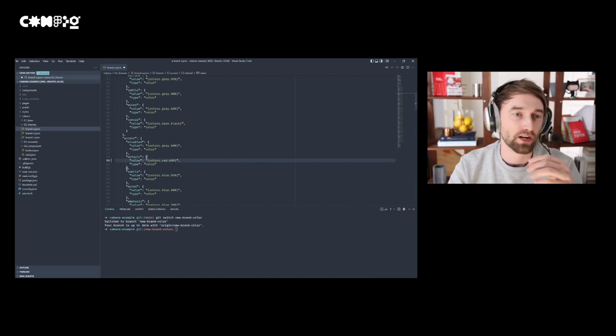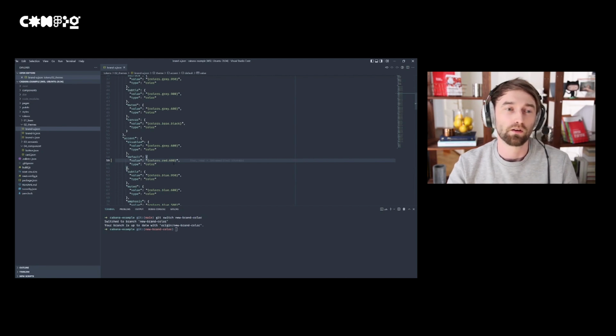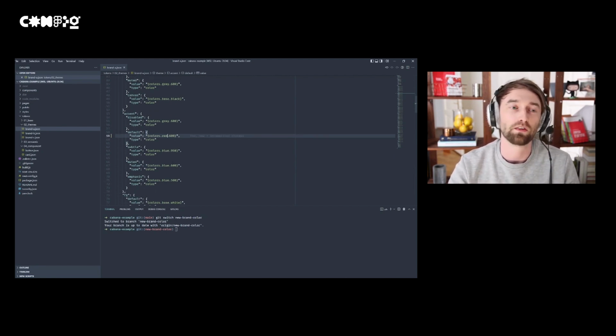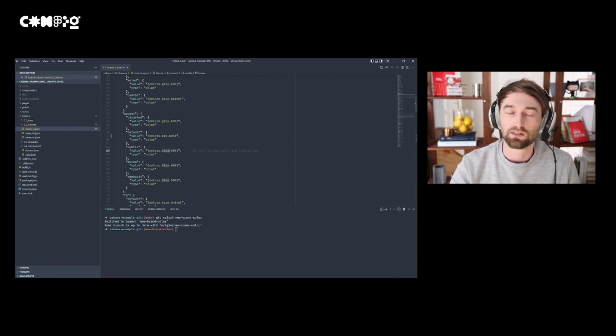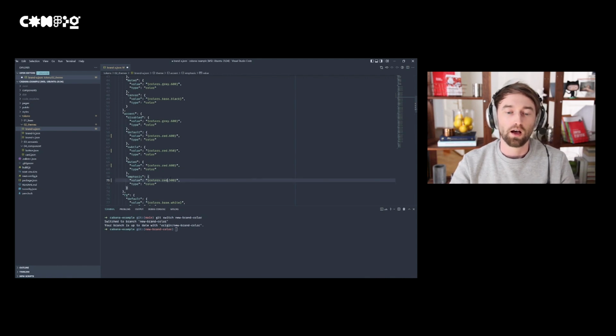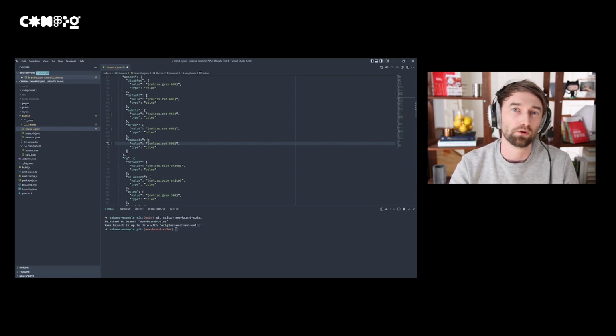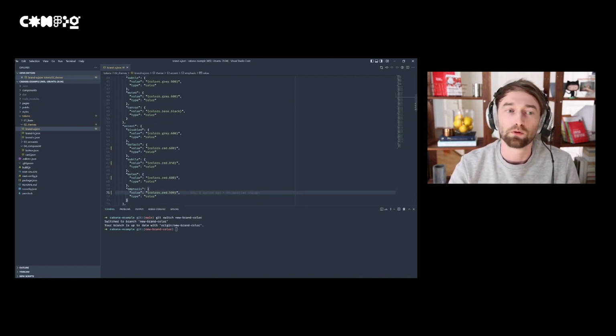So while I was making these changes, you can also see all these other values. These are all types. These are basically design tokens. And I can make changes to all of them, which have an effect on the theme that was being created in Figma. All of these accent colors basically use the same source. So it's this global set of colors, these global variables that we are using. I'm now changing that all to red. And once that is done, I want to then push this again to my source of truth, because ultimately it shares the same source of truth that I was using in Figma. In my case, that is GitHub. So I could just do that and push these changes up there.